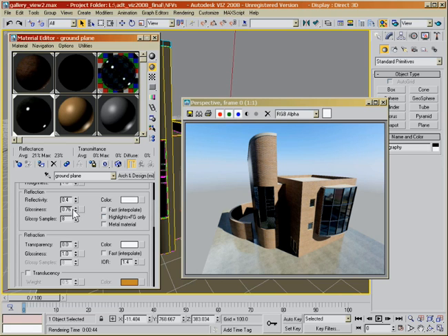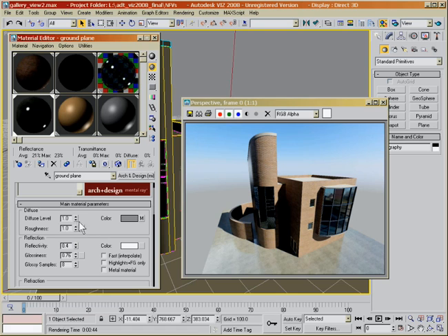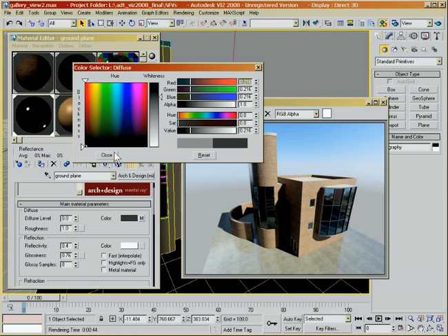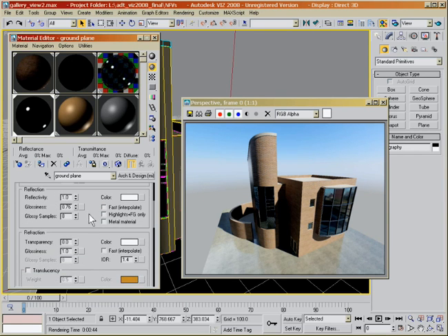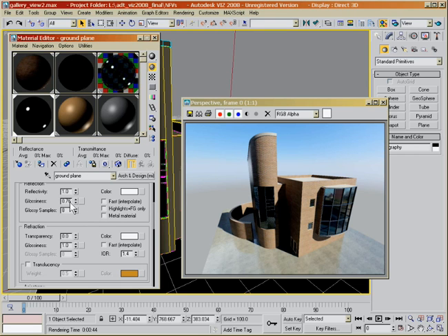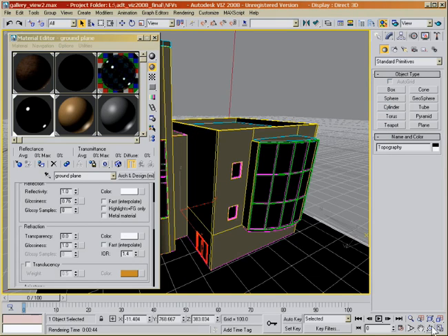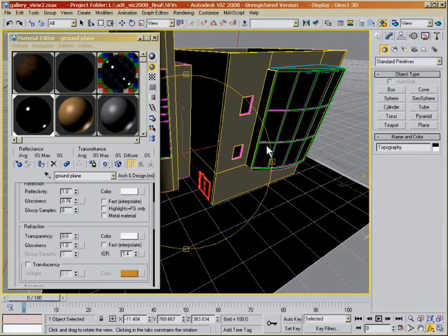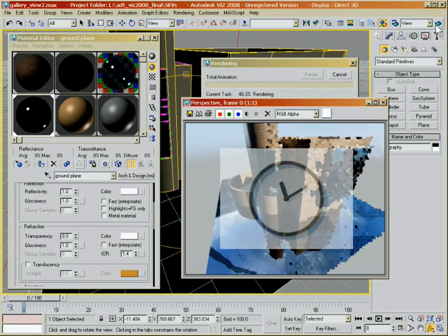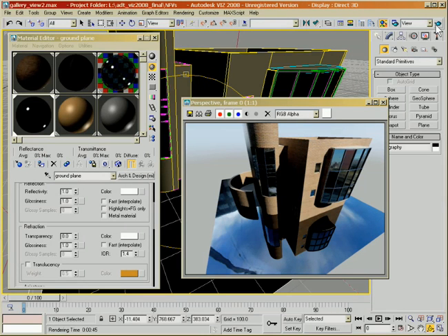of the blurry reflection. If we ignore the concrete texture, setting the diffuse level to 0 and then making the color darker, we can better check how the reflection is affected by these parameters. We also increase the reflectivity all the way to 1, and we can point the camera down a bit. Okay, and now let's first give it a try with the glossiness set to 1.